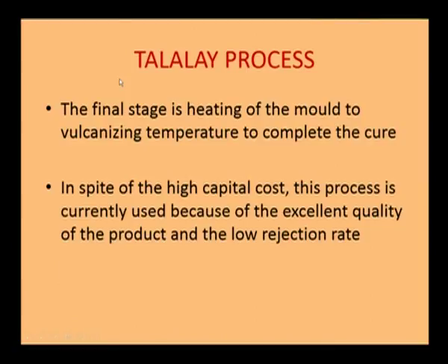In the Talalay process, the final stage is, as in the Dunlop process, that you are going to vulcanize it. You are going to heat it to a higher temperature to complete the cure. In spite of high capital cost, this process is currently in use because of the excellent quality of the product. The end product by this process will be a perfect latex foam for uses like making pillows, mattresses, and carpets.